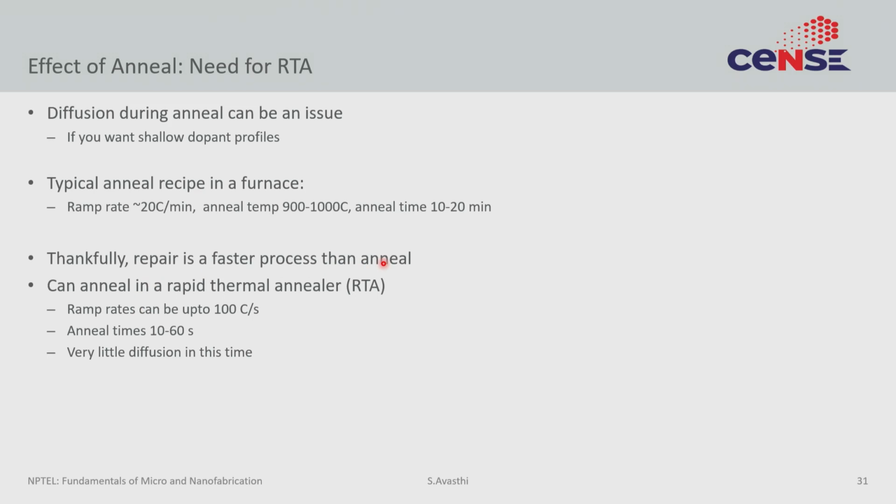So diffusion takes a little while, the repair happens instantly. So this small amount of time is enough for the lattice to repair itself, but not enough for dopants to diffuse.